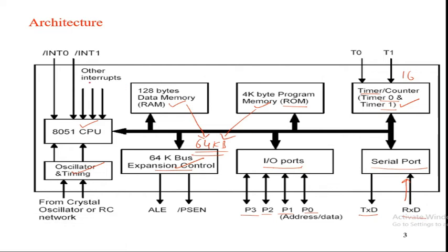Coming to the interrupts, I already told that internal interrupts are there and external interrupts are there. So 3 internal interrupts and 2 external interrupts, INT0 and INT1. The internal interrupts are because of timers or anything else. That is about the internal architecture of this 8051 microcontroller.